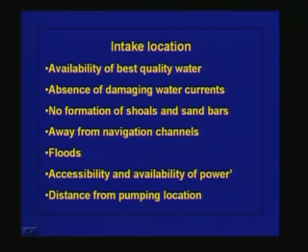Accessibility to the intake structure is also very important, because if it is not accessible, then certainly the maintenance will be very bad. So, accessibility and availability of power are also very important considerations in locating the intake structures.